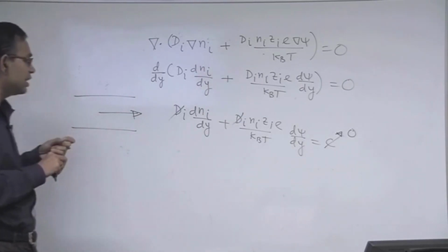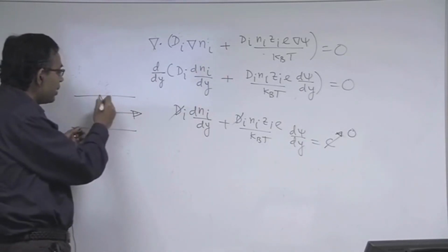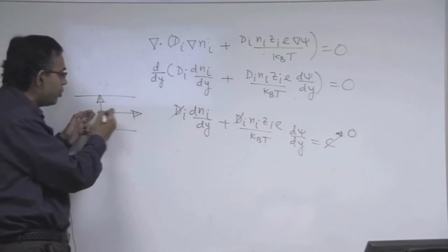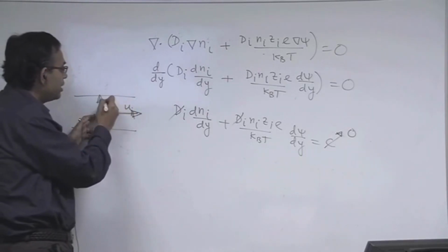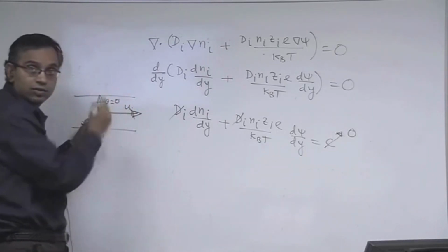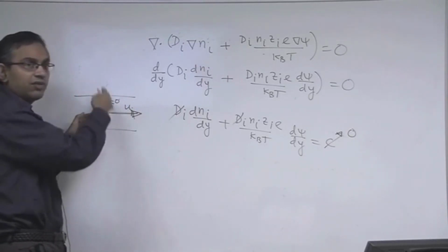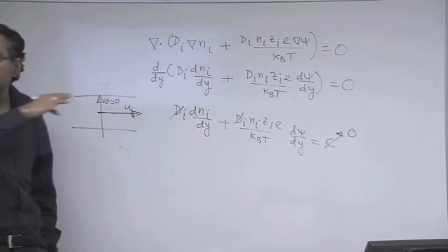The interesting reason is the orthogonality between the direction in which you are applying the Boltzmann distribution and the fluid flow direction. See, you are having the fluid flow in this direction with a velocity u, but the v velocity is approximately equal to 0. So it is an equilibrium picture that essentially governs the distribution in the transverse direction despite the flow taking place along the longitudinal direction.